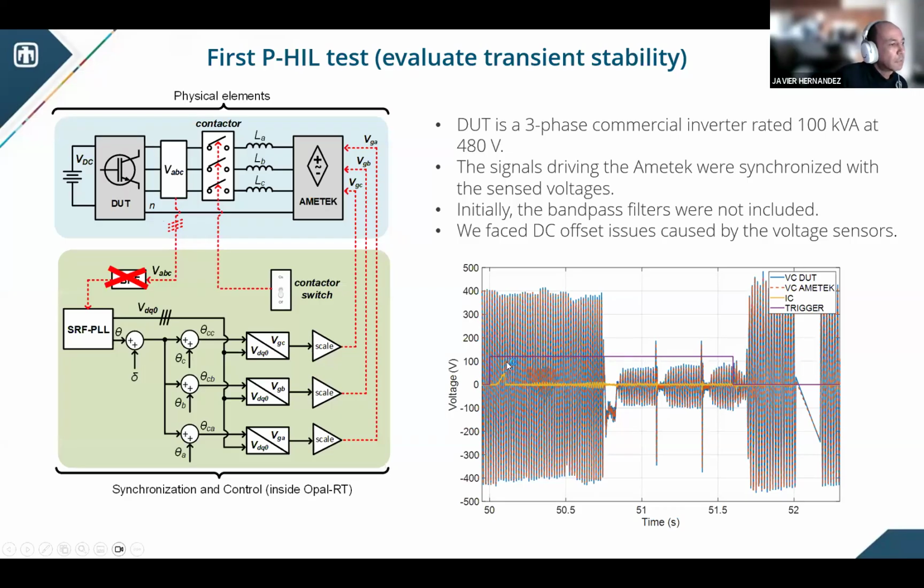And then it stopped providing current, and then the voltages started to do these weird transients and then collapse. And as you could see, what helped us out here is that we programmed the contactor to last only 1.6 seconds. And that may be even too much. So my advice would be 1 second. But you could see how the inverter tried to interconnect several times until it completely tripped off. We didn't damage the device, but at the same time, we had to scratch our heads for, I would say, 2 weeks, trying to figure out what was causing this sort of instability.